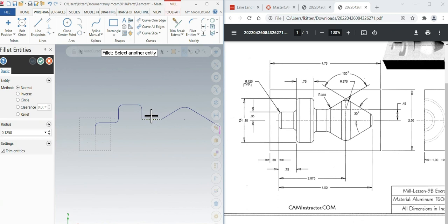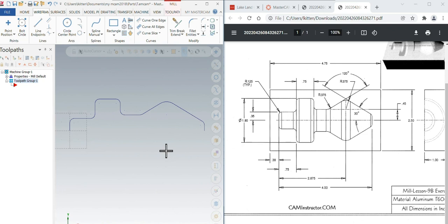That's standard design flow. I'm just working my way around this thing. That big one you leave alone. Where it's already got a radius on it, don't touch that one, of course. Okay? When you get done, it should look just like that thing. Pick the part you want to keep. So if you make a mistake, just hit escape, hit undo, and try again. When you get it all the way done, it looks like that, hit the check mark. Yeah, pick the part you want to keep.